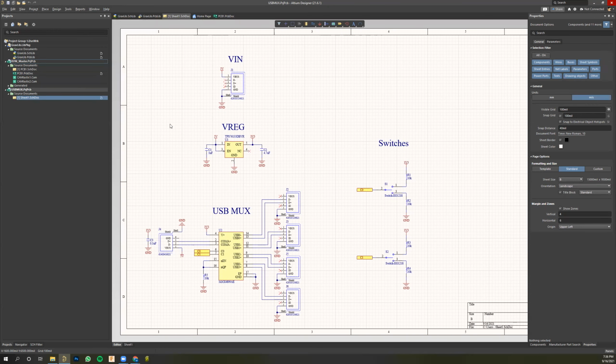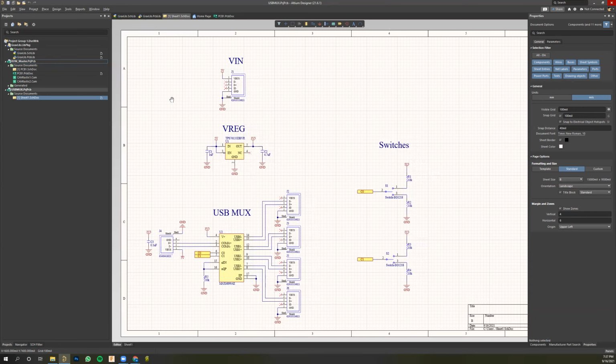So I guess next step, now that we've presumably completed our schematic, would be to move on to creating a circuit board. A little bit of nomenclature here. We often are inclined to call what we're about to make a PCB. That's colloquially correct. It's more accurately a PWB. PCB stands for printed circuit board, and without components applied to it, there's not much circuitry going on. So technically what we're making is a printed wiring board. And then in industry, when you apply parts to it, it is called a circuit card assembly, or CCA, instead of a PCB. So just fun nomenclature for you.